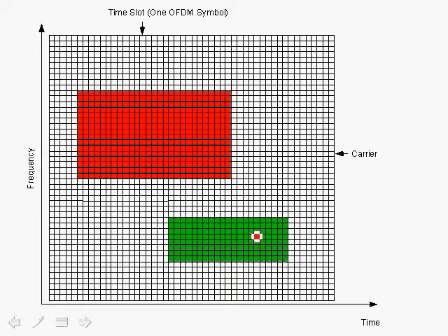So we can see that if a base station was sending multiple OFDM symbols and the subscriber stations knew in advance what their data regions were, then we have achieved multiple access in the sense that the base station is sending data to multiple subscribers over the same packet.